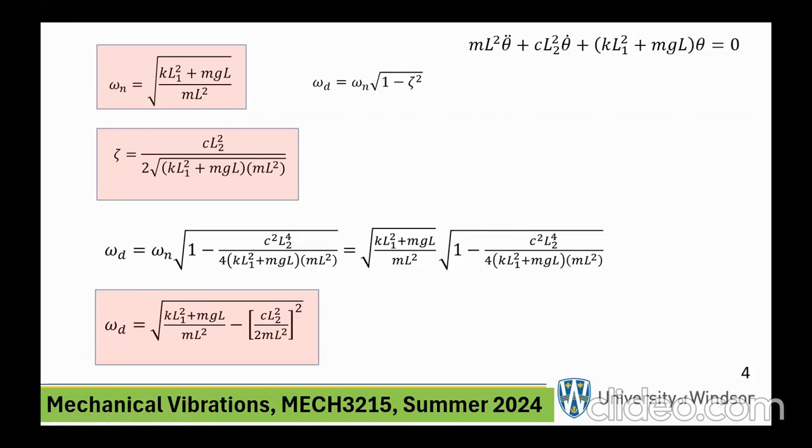So notice that this was a complicated problem, but we effectively reduced it to a single degree of freedom system because we know everything about single degree of freedom systems. Okay, a linearized single degree of freedom system. We know the parameters, omega n and zeta, and we know the response. When we go back, we found the solution to that equation. We found an explicit term which involves a decaying exponential. There was sine, there was a phase angle, there was an amplitude, etc. So we know everything. All right.